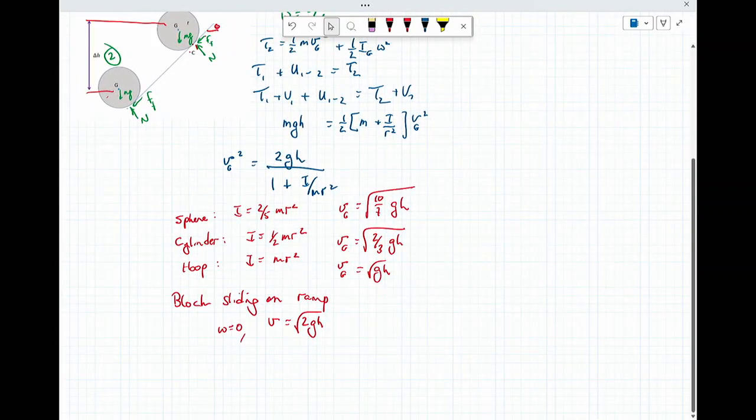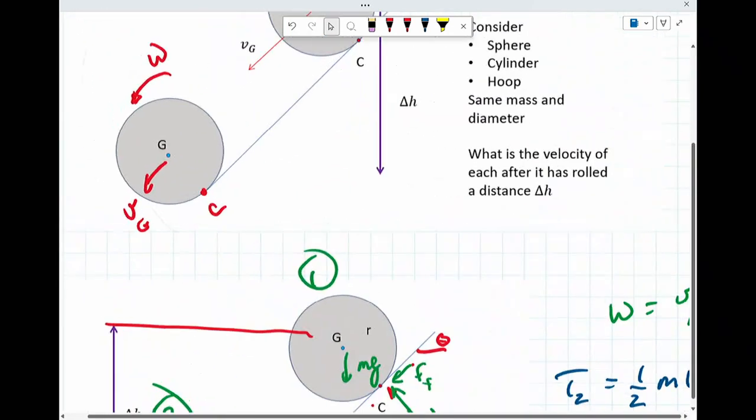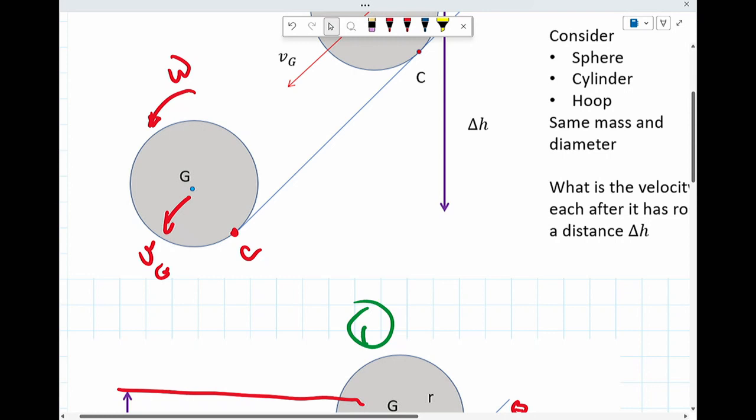Questions? How do we know the friction is going down the ramp? We know the direction of rolling. It's rolling without slip. So, right here, I very expertly pre-drew this, and I knew that the direction of the rolling is counterclockwise. So in order to oppose that motion, I have to have a friction, opposed in this form. So it's always looking at the rolling. Now, if it were slipping down, say a block slipping down, then the friction force would change directions.